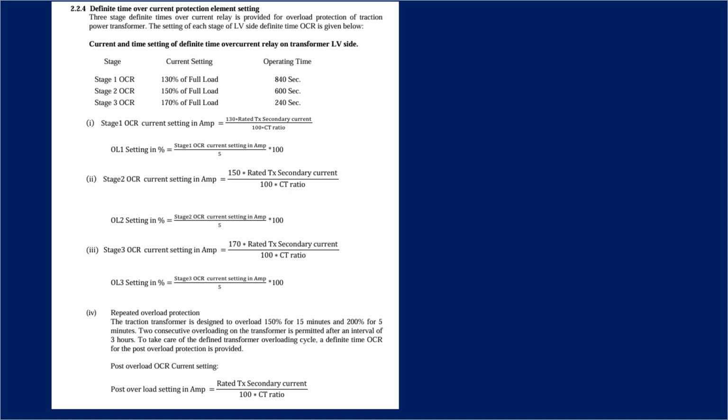And the time also changes with this. The HV and LV times taken are also different. Then what are the other changes? The HV side current is set at 1.8 times, 1.9 times the rated load HV side current, and here it is taken as 1.9 times the rated load current of the secondary. Okay.